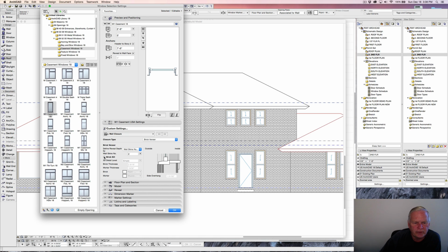We are going to be using a brick sill, and we want it to be a detailed one, so we actually see some thicknesses. The brick thickness, we're going to set that for 2 5/8. And I didn't. Now, what happens there, just so you know, is it doesn't wait very long for you to input things. So when you do start, you've got to type 2.625 inches, or it throws feet in there and you have to start over again, as you just saw. Mortar thickness, I'm just going to make that 1/2 inch thick, or 0.5 inches.